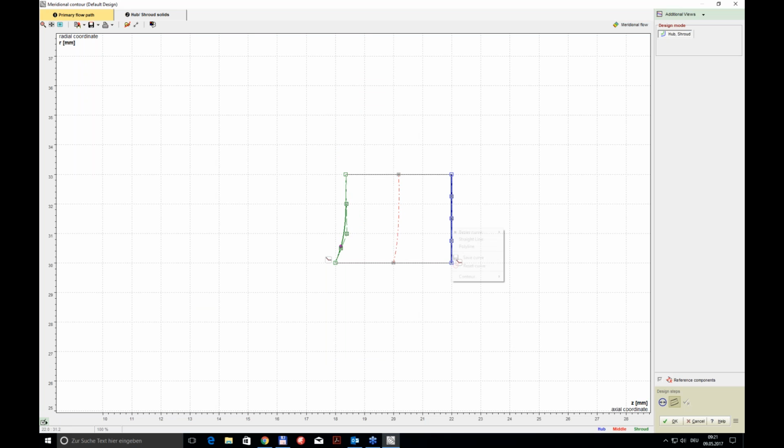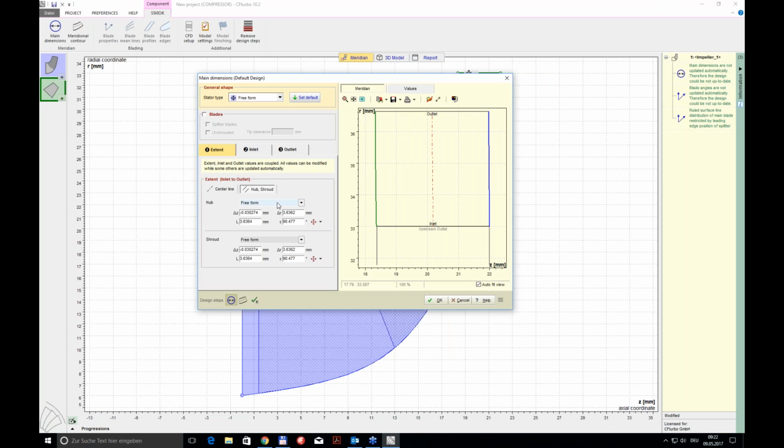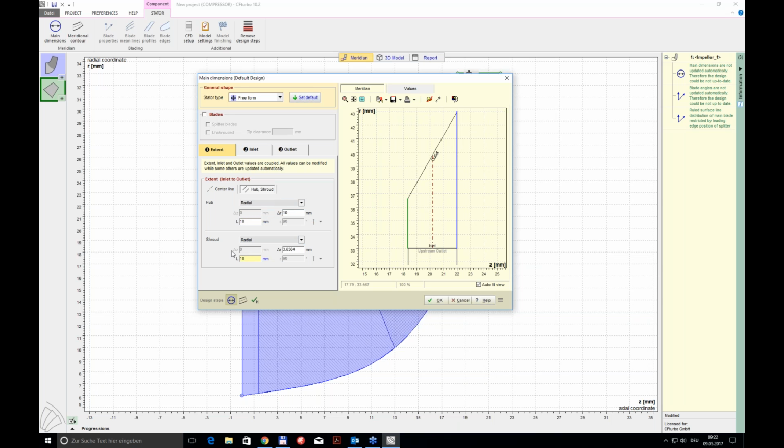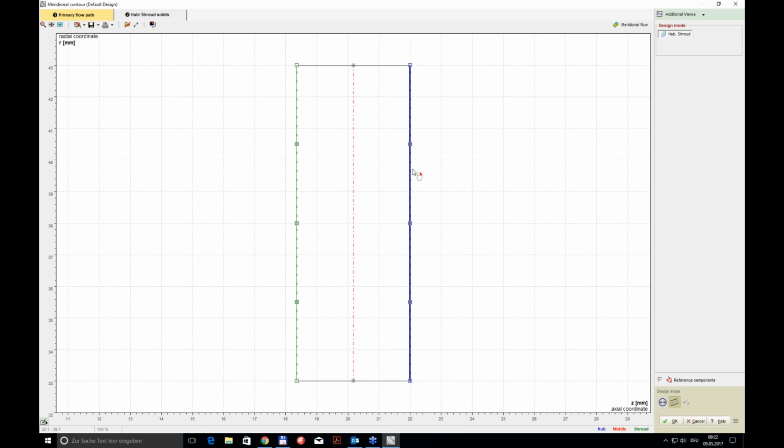Make it less hard changing, and so that's probably the pinch type diffuser, and then I want to have another diffuser that should have parallel walls, and again it's radial, and it should have a certain length, so for instance 10 millimeter at hub and shroud, and I don't need this Bezier shape because it should be just parallel.